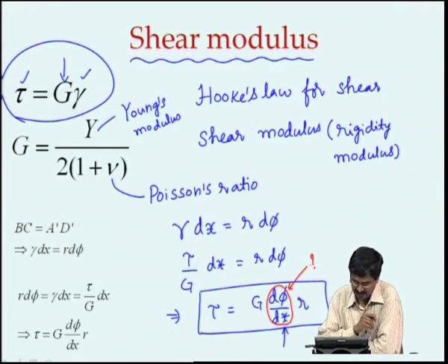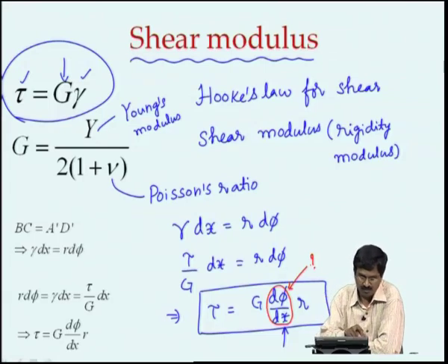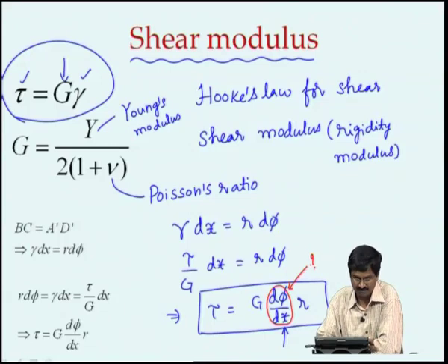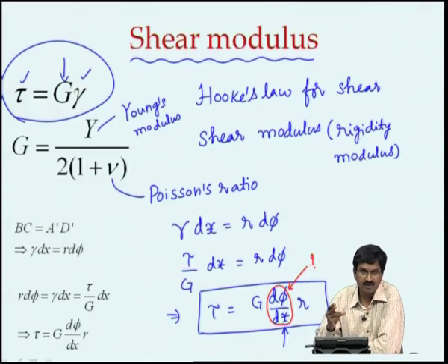Here you notice that we introduce two things, the shear stress tau and then shear strain. We know one quantity that relates both of them, that is Hooke's law, but in order to determine statics we need Hooke's law and we also need the equilibrium equation. So, that is what we will next go to in order to find this rate of twist along the axis of the shaft.